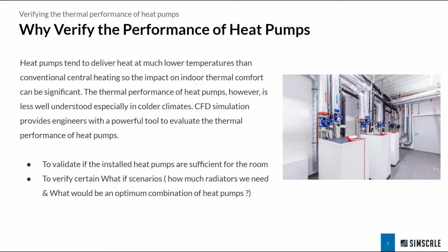CFD simulations provide a huge variety of insights regarding the performance of heat pumps. When we are evaluating the thermal performance of heat pumps, we'll be able to validate if the installed heat pumps are sufficient for the room. On the other hand, we can also verify certain what-if scenarios, such as how many radiators we need to achieve thermal comfort in the entire space, or find the optimum combination of heat pumps and radiators to ensure thermal comfort of the occupants with a particular design criteria.